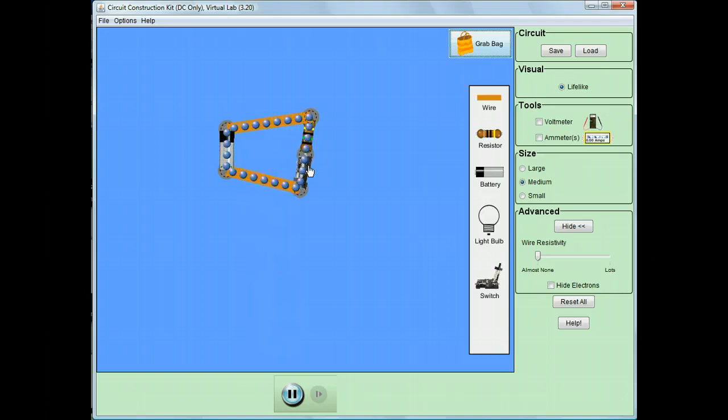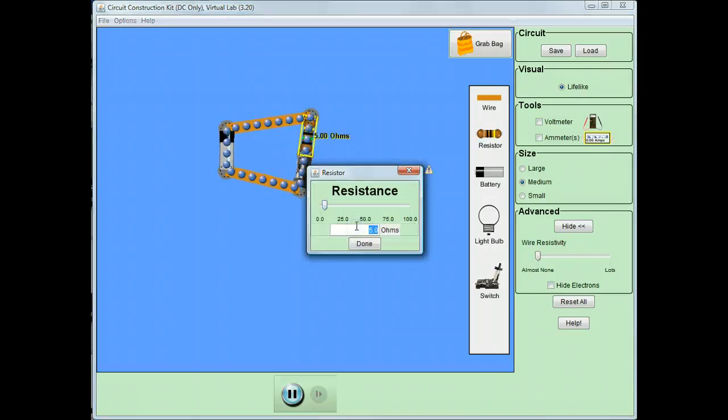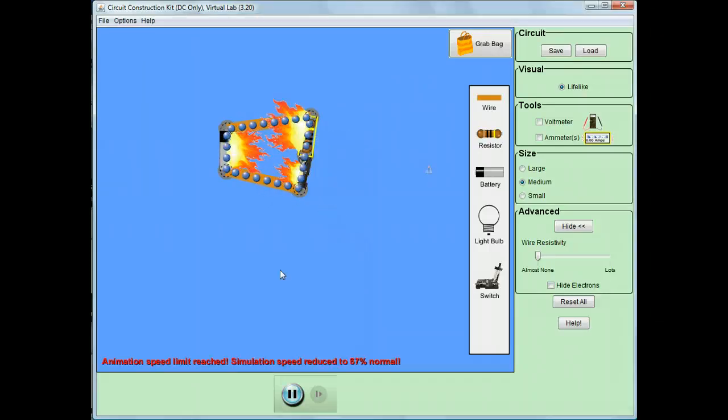One last thing, and it's kind of a word of warning. Let's say that I've got this done here and I want to just make this, let's say 0.5 ohms. It doesn't like this. Okay, it's basically said that you've just burned everything up. There's too little resistance, you're burning up the wire. Very, very bad news. And if this was a real experiment, you might have blown out the battery, or you might have burned out the resistor, or the wire might be burning to the point where it's melted in half, and then current will no longer flow. So it's kind of like a self-correcting situation, but it's self-correcting in a very negative way because you've just destroyed your lab equipment.